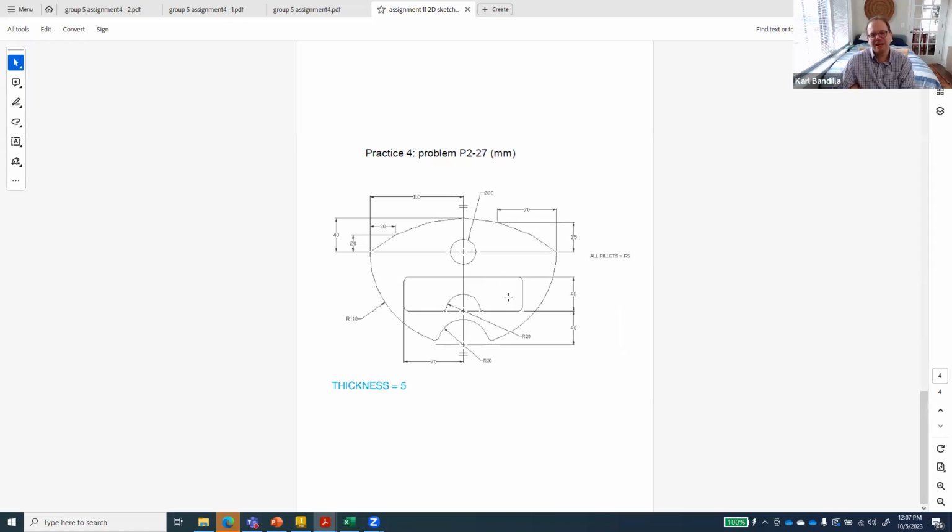And then the last one is this kind of Power Rangers mask, I guess, in a way, right? This one is very much, especially the top part here, right? Draw one of these and then you mirror it over to have the other part. The rest does not really help you to have it be symmetrical. But for this line, yes, so I would start by just drawing this line, copy it over with that line, then you can draw the half circle that goes onto it, and then you can add this rectangle here, like, draw a circle, trim out the stuff that you don't need.